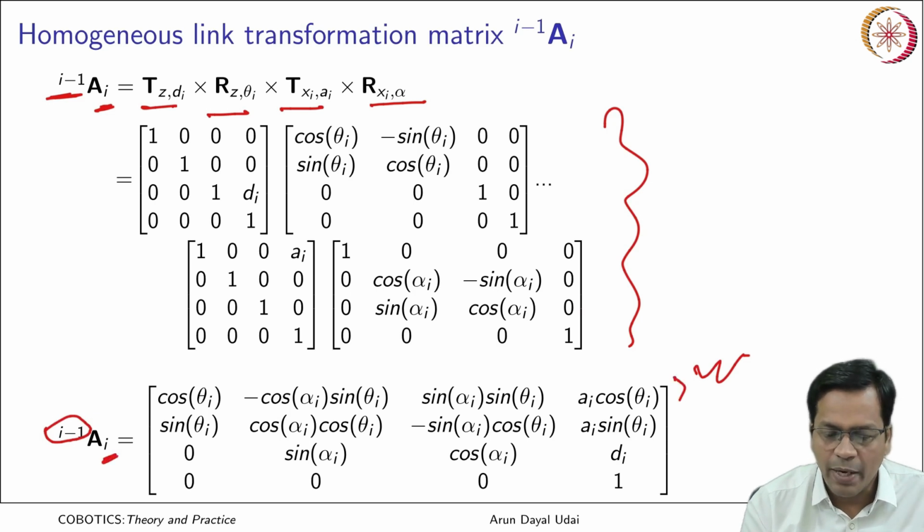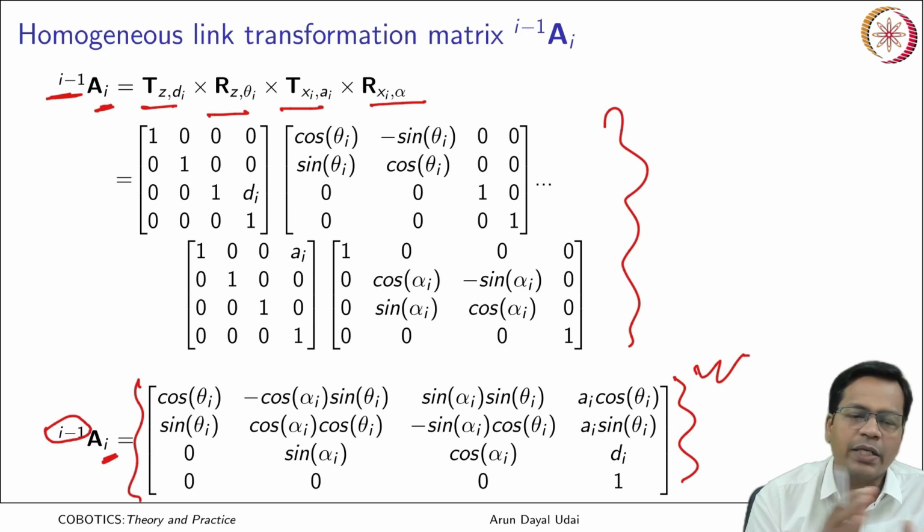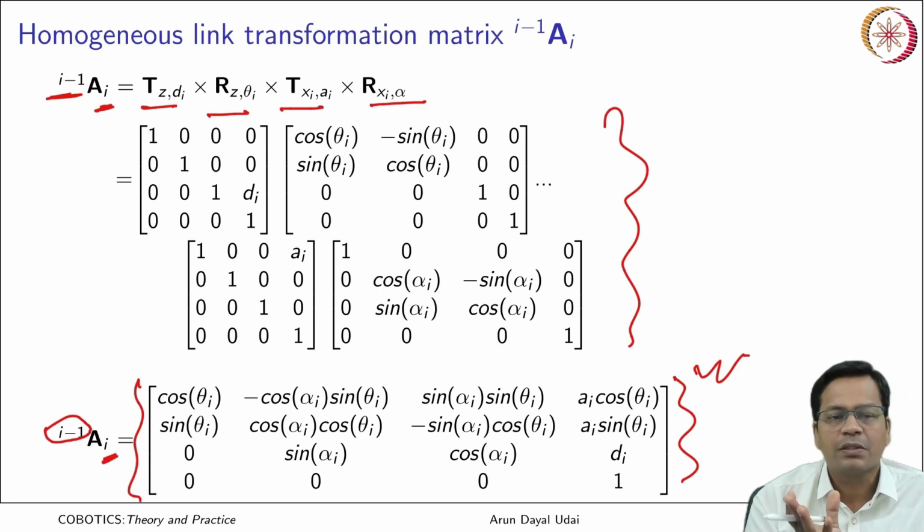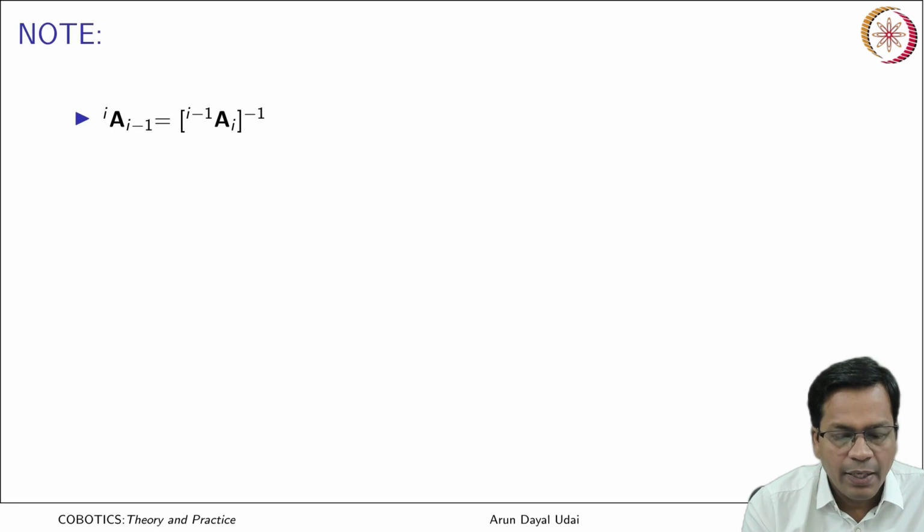Okay. So, this is a combined transformation for all the translations and rotations that defines the link shape. Apart from theta_i that defines the link position with respect to the previous link, the remaining are d_i, alpha_i and a_i, that is giving you the link shape and its structure. Note here, A_{i-1,i} is equal to the inverse of A_{i,i-1}.